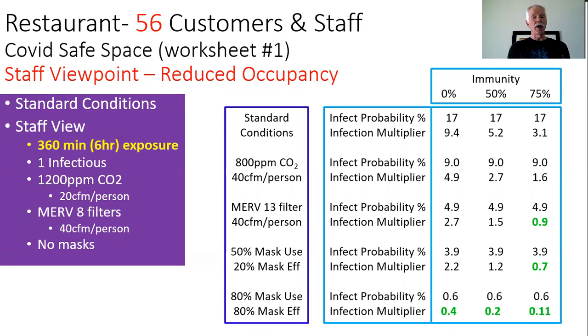The second is that as you try to increase your ventilation, there may be reasons why you can't do that at this point, or the building is physically constrained so you can't bring more fresh air in above a certain level. If that's true, then in order to get to 800 parts per million, you reduce the number of people allowed in relative to the amount of ventilation that you have available. That's how you get to this level.